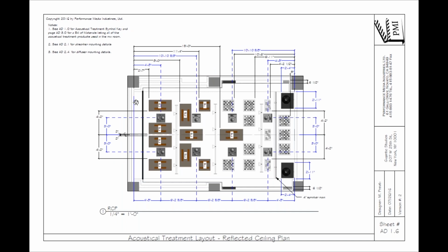So that's the ceiling in this room. Again, this is where the front speakers are. These are the top channel speakers, and then all around the front part of the room is absorption. The back is diffusion. So that's the one place where we will cluster absorbers in one place and diffusers in another place. We basically want as much support of the diffused energy of the surround speakers as possible towards the back of the room. That's why the back is done that way.